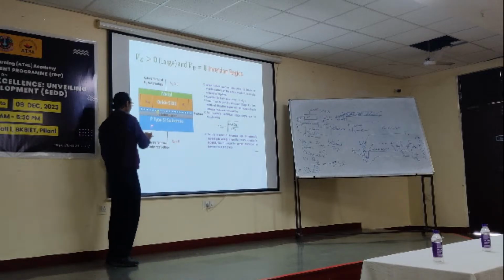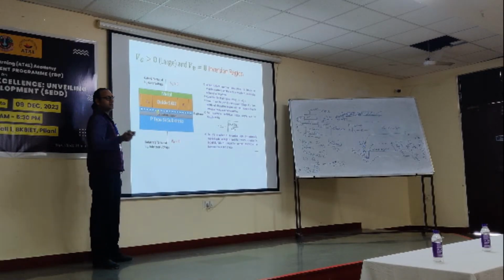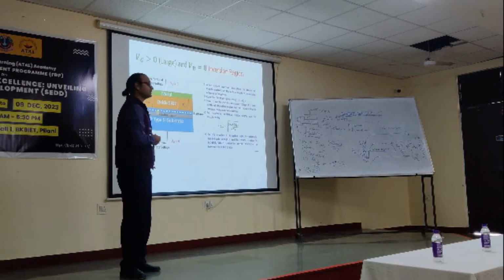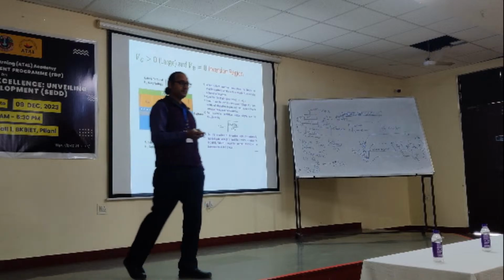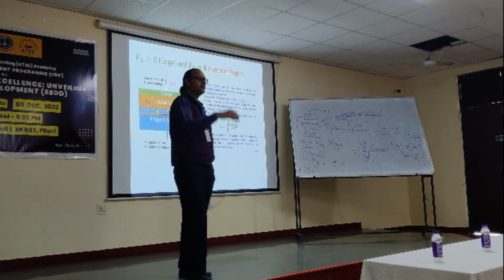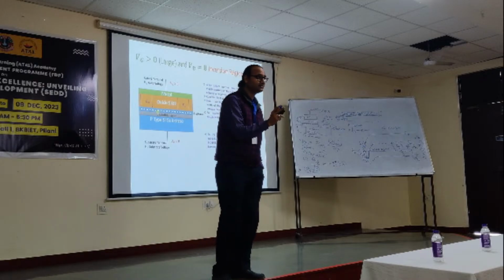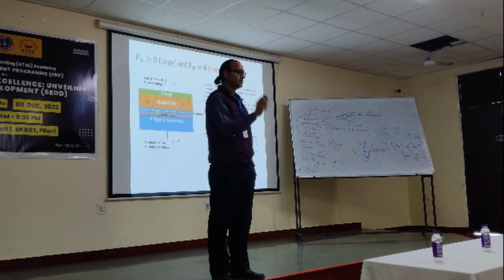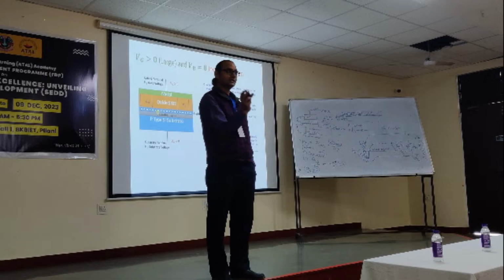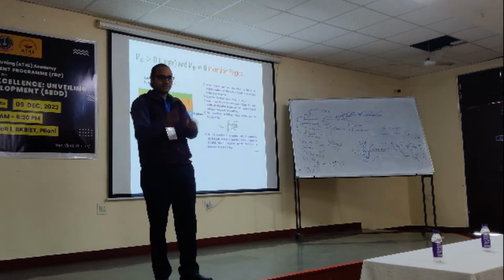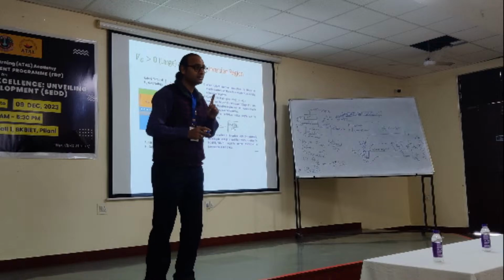See, this is P type, right? P type means majority of charge carriers are holes. So depletion means obviously deplete. What is the definition of depletion region? It is depleted of majority charge carriers. In a diode also, we should specify very clearly that depletion region means depletion of majority charge carriers near the junction. It has charges, but they are minority charges.